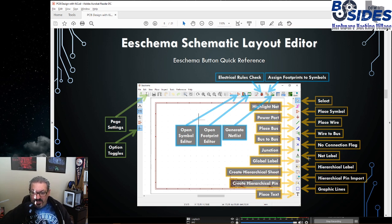You can put in junctions, and use labels to label nets. So if you have a ground net, you would label it ground, something like that. Now we have global labels, and global labels are different than just the net labels. Global labels are actually used in a schematic to allow us to connect different parts of the schematic together without having to draw lines that are going to crisscross. So we want the schematic to be clean.